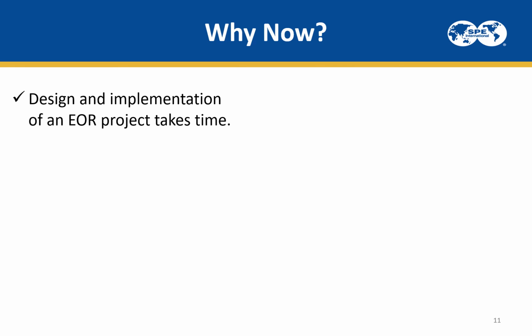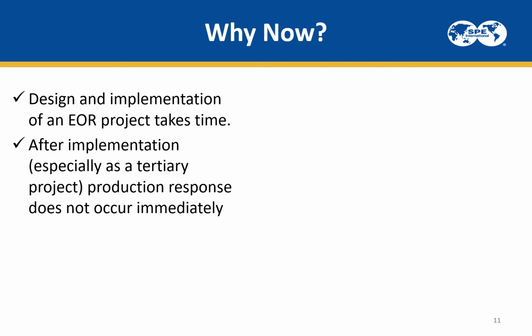Why do we need EOR now? Because the designing and implementation of any EOR project takes a lot of time, so we have to think of EOR as early as possible. Even after implementation, the production response for the EOR will not happen directly. When we inject, from injector to producer, sometimes it takes a couple of months, even sometimes a couple of years to get a response from injector to producer.